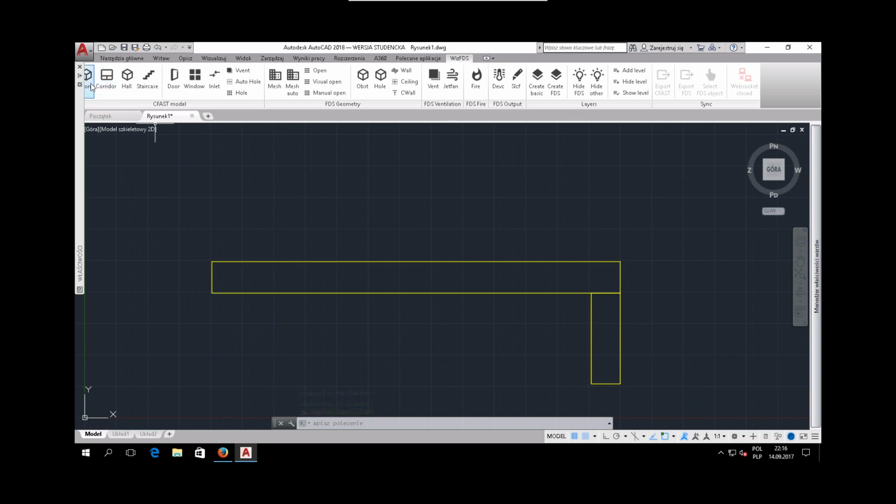So we select room, and once again, which level? This is the first floor, so 0 is the Z-minimum for this room. So enter, and then this is Z-max. In our case, because there is no technology in this room as in the case of the corridors, the Z-max for rooms is 3 meters. Okay, so we can now draw rooms using the AutoCAD plugin.